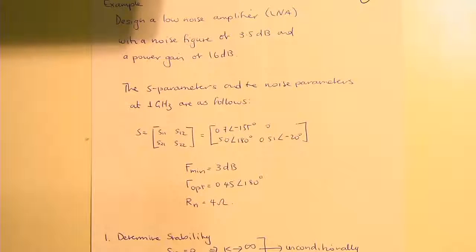Essentially, a resistor or something at the drain, but yeah, the source is connected to ground. Okay. Now, that's going to be important later on when we talk about oscillators, and depending on the amount of feedback that you want and the level of oscillation, you probably wouldn't want it in common source configuration. Common source is great when you're making amplifiers, not necessarily great when you're trying to build oscillators.